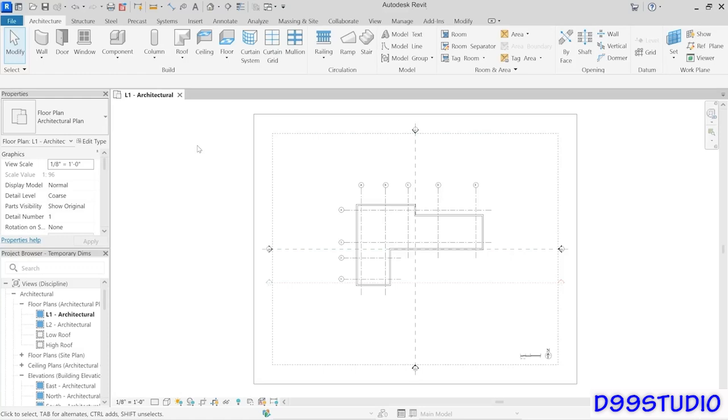In Revit, what you typically want to do when you're facing a layout task is quickly and roughly lay out the geometry first, and then come back and slowly and progressively refine it into its more correct configuration. You can think of that as you start with a really rough idea and then progressively refine it, or you start with a really simple rough sketch and then you modify that sketch.